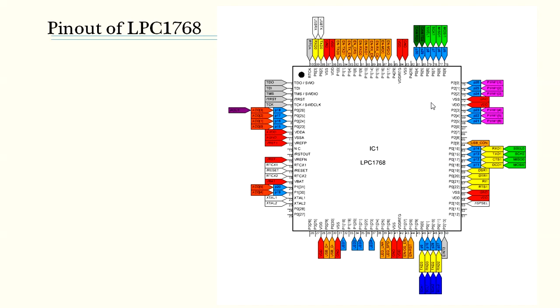It is a normal GPIO as a simple input output. Then you have the first alternative, second and third. And the whole of the programming of this GPIO is managed with the pin select registers and the GPIO registers. The details of the GPIO registers are discussed in the next lecture on GPIO registers.